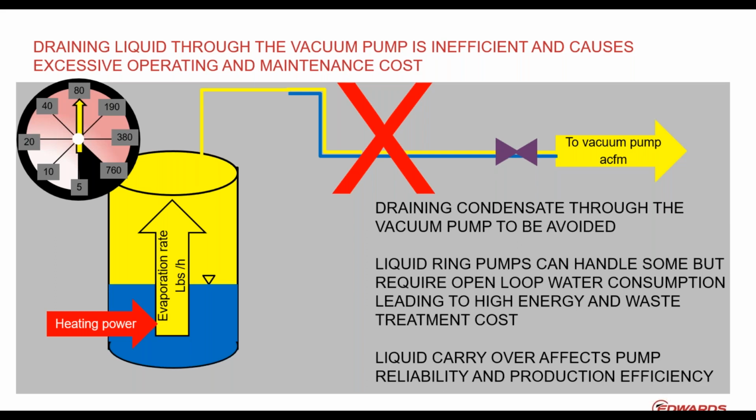This is the big one. You can imagine liquid drain pumps, again, handle some of it. An oil seal pump or a dry pump don't like that at all. And it's not because they can't stand it mechanically, they can, unless you find yourself changing oil every day, because you have this carryover that is affecting your pump in doing what it's supposed to do.